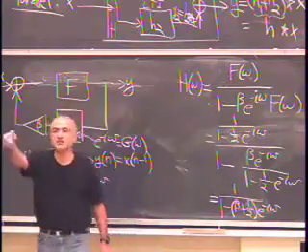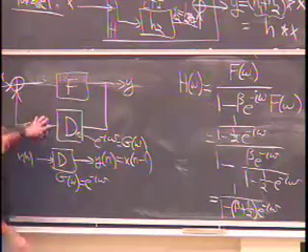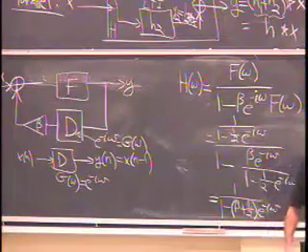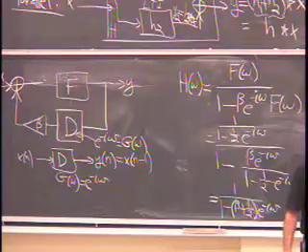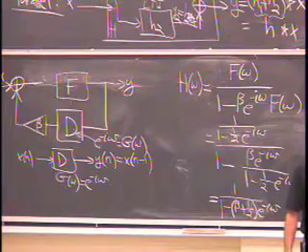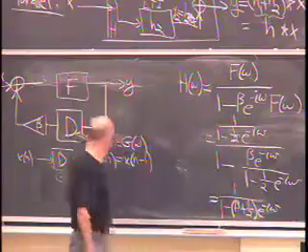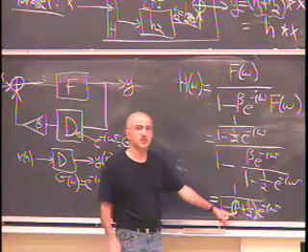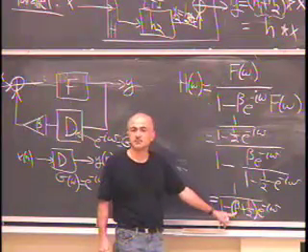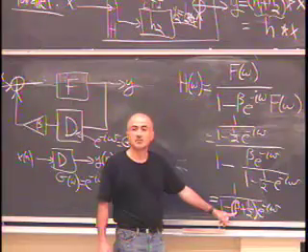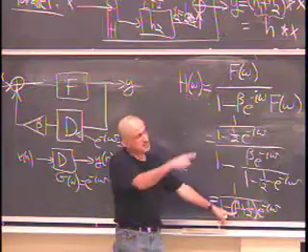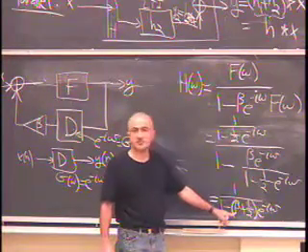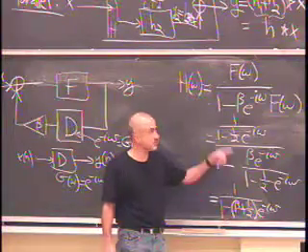Now, if beta is a switch, if I have a choice of what to do with beta, can you turn that low-pass filter into a high-pass filter? Can you do that? What do you do with beta? Give me a value of beta that will make this a high-pass filter. Negative what? No, it can't be negative 1/2. That takes that x to the origin. So it's got to exceed 1/2. So if it's, let's say, minus 2/3, then this will turn into a high-pass filter.